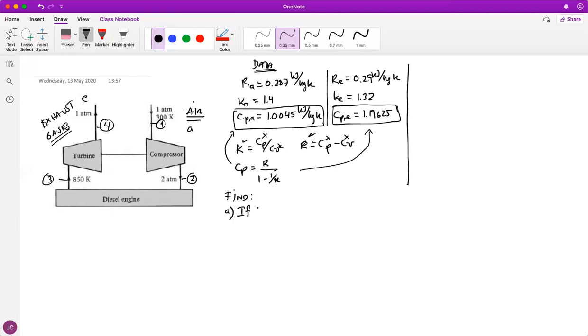It says that the isentropic efficiency of the compressor equals 1, and the efficiency of the turbine equals 1, that is, these two machines are isentropic, ideal, working reversibly. It's not the same thing, but so far we can say that because I'm thinking these two are adiabatic. Therefore, find the pressure at 3.